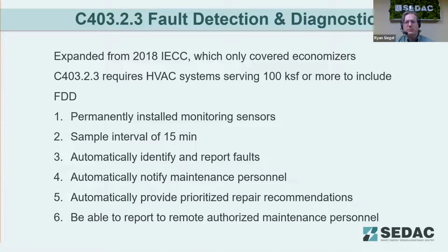Also, we have greatly expanded fault detection and diagnostics. Previously, it was just for economizers. Now for larger buildings, so this is over 100,000 square feet, now you have to do building automation system fault detection and diagnostic.